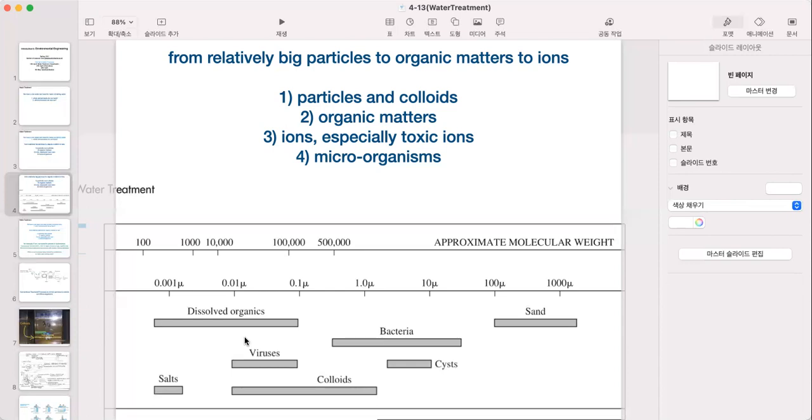So if we insert a positively charged chemical into the water having the colloid, it bridges one colloid to another through these coagulant chemicals to be destabilized to form a floc, and then they can be settled down to be removed out of water. Okay, that's the coagulation process, flocculation and coagulation process.